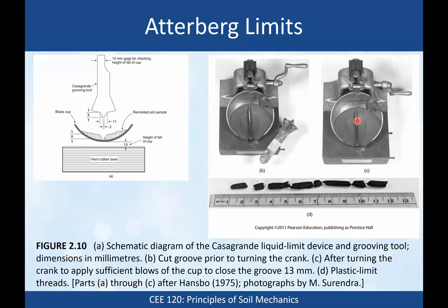I can no longer see the shiny part. It only has to close on the bottom. It doesn't have to collapse all the way in and touch on the top. As soon as you can't see the brass anymore over a 1 centimeter or 10 millimeter length, then you're done. And you count the number of taps that it's taken to get there. Okay, and then you repeat that.